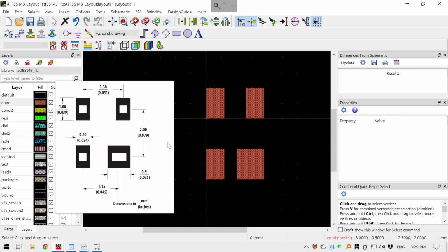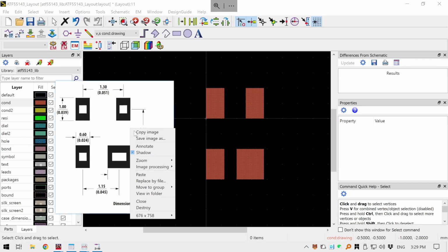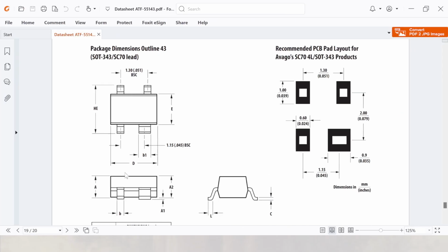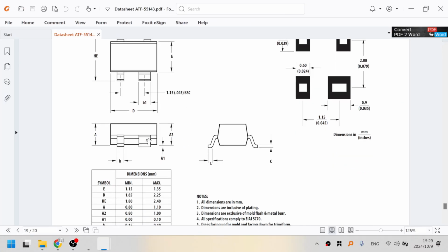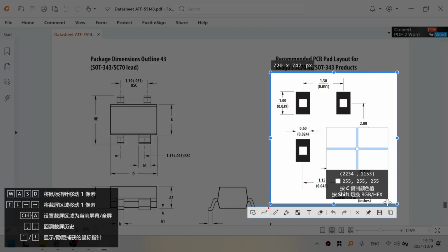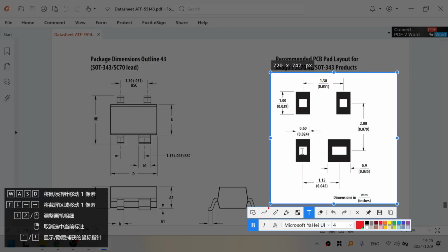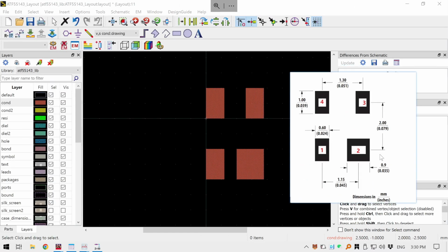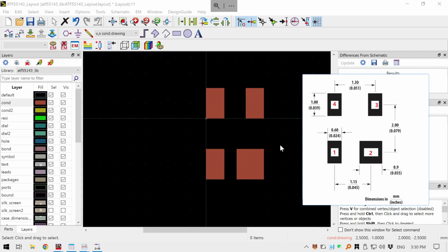by, so also in the layout we should note that there is some requirement of the orientation. So you see in this kind of transistor, the left bottom pin is the first pin. So I can add some text here. This pin is the first pin, and this is the second, this is the third, and this is the fourth. So this orientation matches the port we assign in the simulation model.